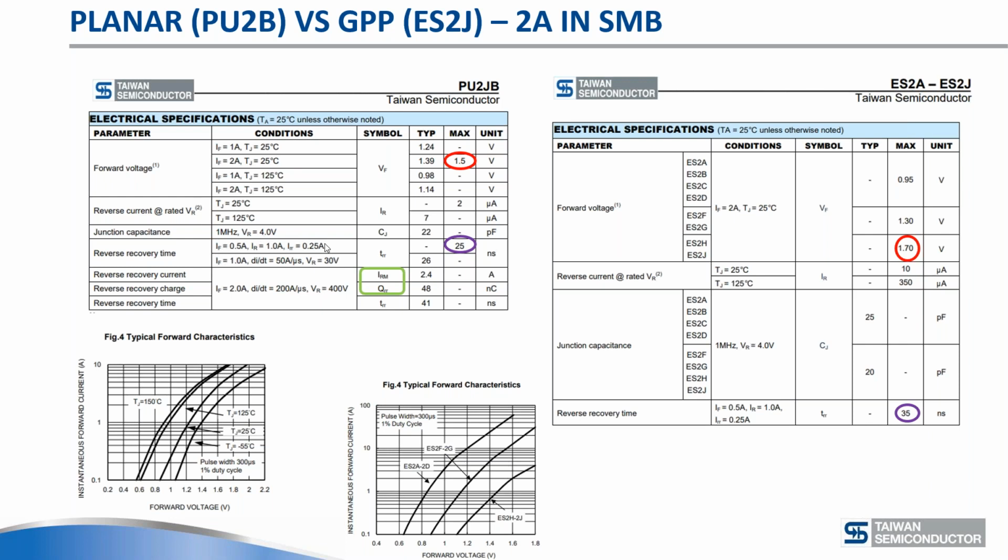You can fairly say that these test conditions are very far away from how a designer may use the diode. So this information may not be so relevant for the designer, although the comparison between 25 and 35 nanoseconds is. What is a real application condition for a designer would be to take the maximum current and turn it off at 200 amps per microsecond, or you can even do it faster with an IGBT.